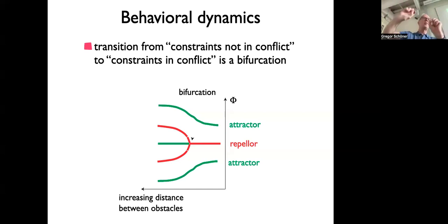When you have obstacles, if it's physical obstacles, this is the distance between the symbolic and sub-symbolic approach. In the symbolic approach, we're really talking about objects in the world, the obstacles. And those, of course, have this property that if they are far, the angle between them is small. So I will tend to be somewhere here, where I will be repelled from the average direction. If I get closer, they will move further away. And then I can figure out whether I can pass through or not, which depends parametrically on how large they are. And that will actually happen.